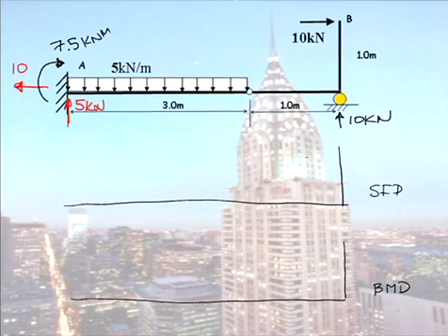So what I'll draw here is an eye, just to indicate when you come and draw your shear force diagram, you'll be looking at it from where the eye is. So I'll draw this part for you. You would start at the left-hand end, which would be the top. You would step up a value of 10, move constantly down, and then because of this 10 reaction here, that would return to 0.